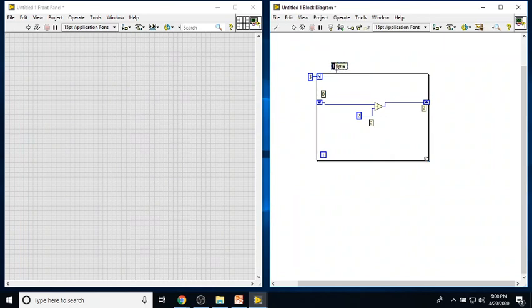Right? So on the second iteration, this loop is going to iterate 3 times, right? Second time, what is going to happen is, this value 2, which was written on the right hand side shift register, will internally move to the left hand side shift register, and this will turn into 2. Before it was 0, the reason is there was no data inside. Now you wrote the data on the right hand side shift register, right? So this acts as an entry, and this acts as an exit. So the data 2 comes here, 2 comes here, 2 plus 2 will be 4, a new data returned to your memory will be 4. So this is what happens at the end of the second iteration.